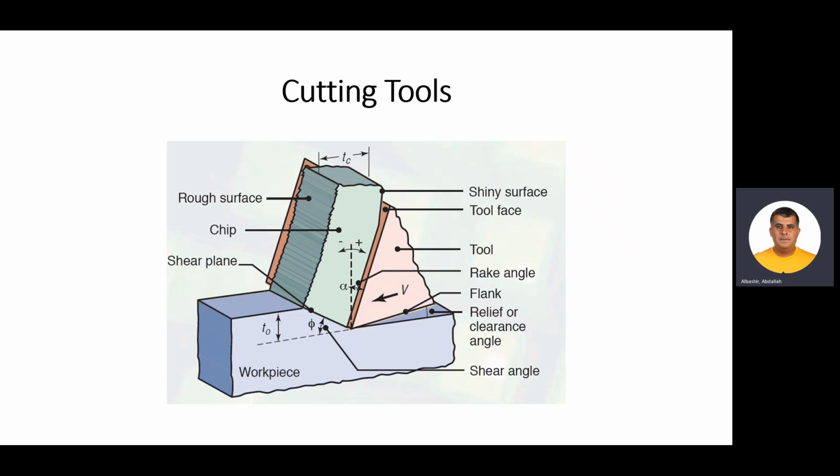So it has a depth inside it, and it moves toward it. So it will form a shear plane. On that shear plane, on the side that is against the tool, there will be a tension force that will cause the fracture, and on the other side, there will be a compression force. And you'll see how the chip forms.